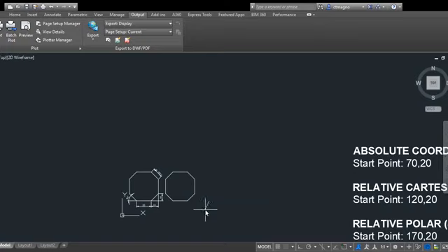So back to the drawing. Set the first point at 120, comma 20. Then I'm going again @20, comma 0. Then 10 to the right and 10 up, so @10, comma 10. Next is @0, comma 20. Then @negative 10, since I'm moving to the left, and then up in y at 10, so @negative 10, comma 10. And then I'm going to the left of x at negative 10, comma 0. Oh, sorry. It's supposed to be @negative 20, comma 0.